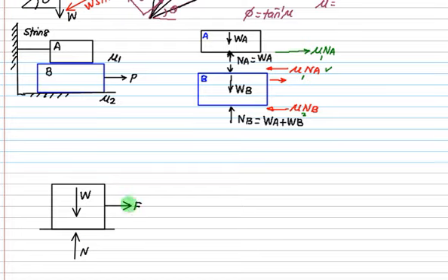And I am applying a certain force F. Now this force is not sufficient to overcome the friction force, which is mu s times N. So I don't have this value of force. Suppose this one is 100 Newton, so the normal reaction is also 100 Newton. And suppose mu s is 0.2. So we have a 20 Newton force.